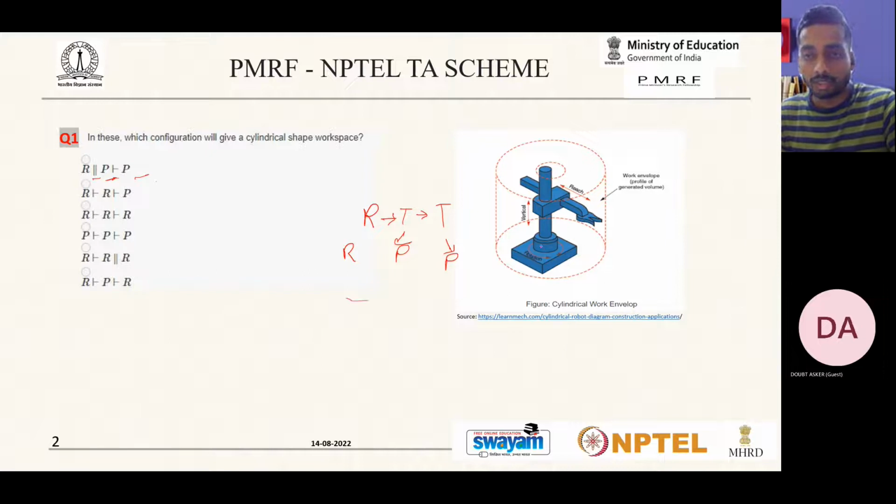If you do the rotation, you'll have a coverage like this, so the whole thing will move in a circular fashion, but that doesn't mean it will be cylindrical. For a cylinder, these circles should be traced back and forth, so there should be a translation, or a P. For this prismatic motion we use Z, and the rotation is also along the same Z. Of the two frames you consider for the DH parameters, Z1 and Z2 will be parallel.